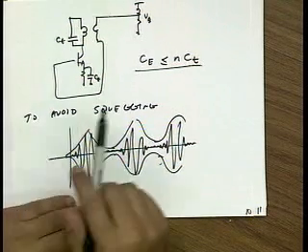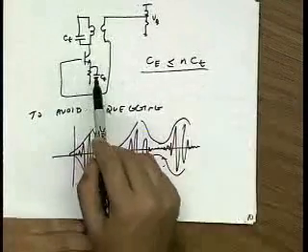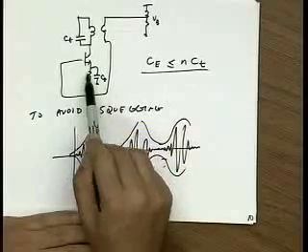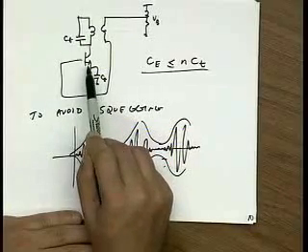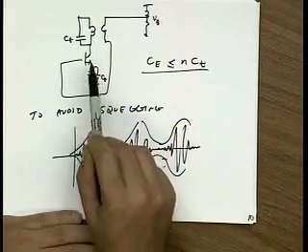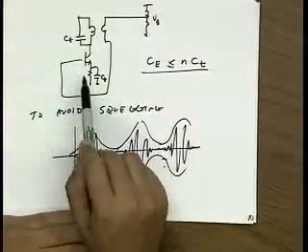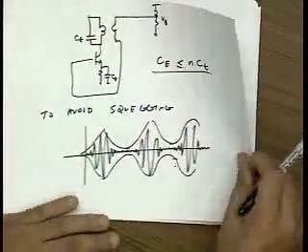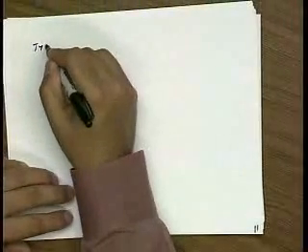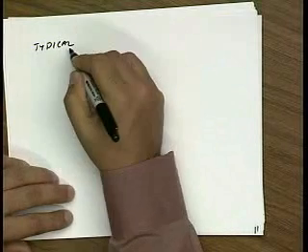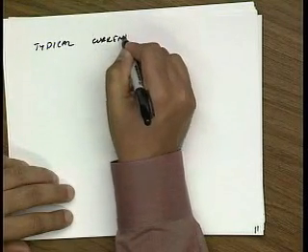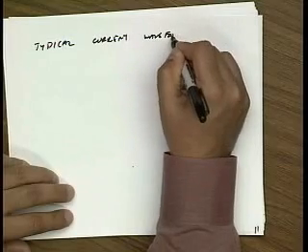Well, what's happening is that the circuit can't reach steady state, because remember that putting this resistor here tends to reject increases in current, right? And so this circuit, in order to work, let me show you what happens. Let's look at some typical waveforms.